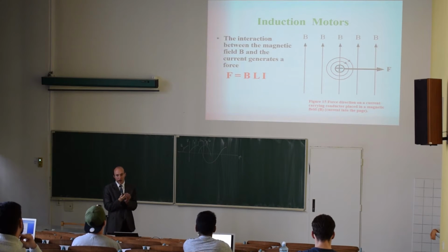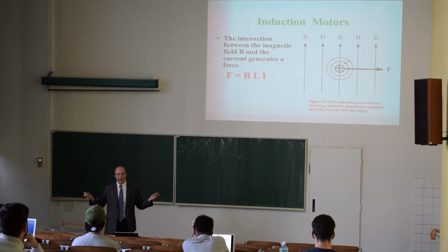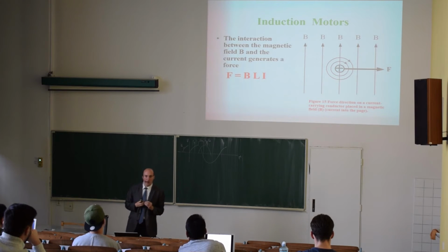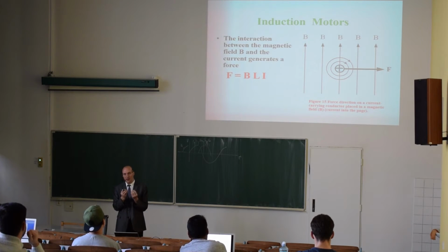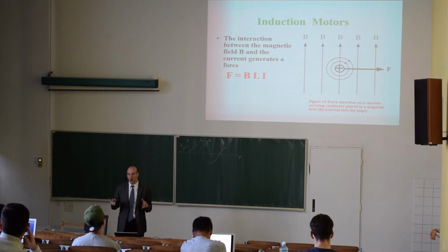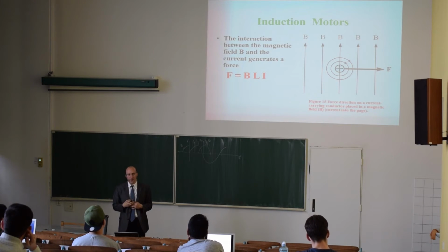Length, that's clear. If I make the rotor longer, it will have a higher torque because I will act on a higher distance. But obviously, if I made a very thin rotor with a really long length, I would have mechanical problems, like vibrations, for example.